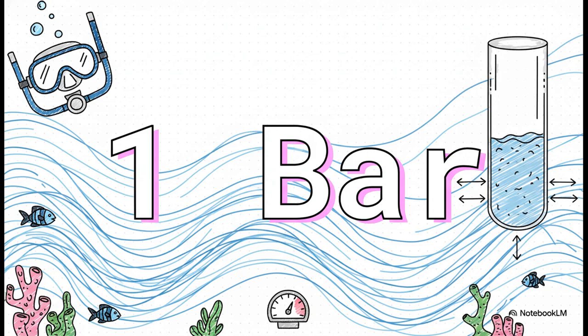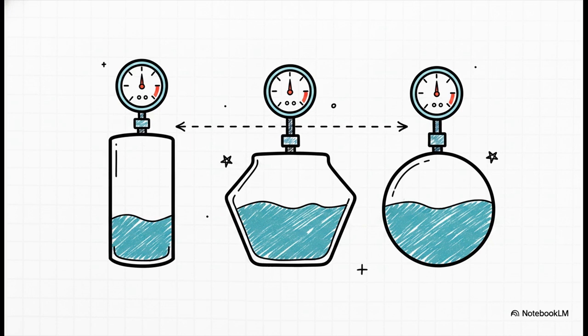So the really crucial point here is that by always measuring at the top, engineers get a consistent, totally reliable baseline. This baseline purely reflects the gas pressure that's driving the process. It doesn't constantly fluctuate every single time the liquid level rises or falls, and it isn't skewed by the physical shape or height of the vessel itself. It's just clean, simple, and standard.